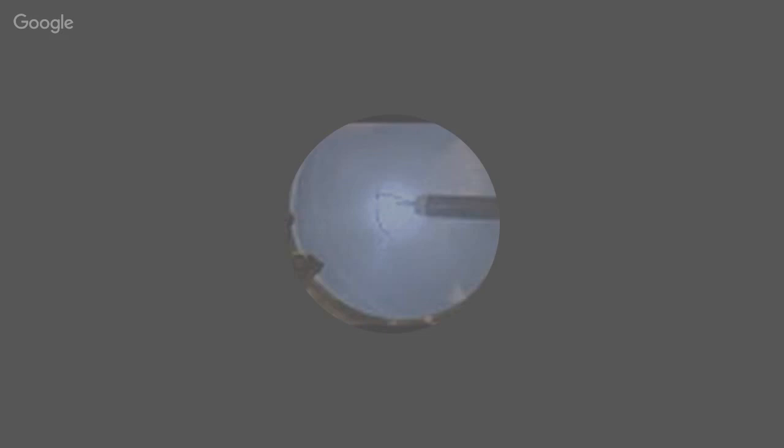So this is another demonstration problem. Here we are plotting density contours inwards in an annular region between 5 and 50. And this kind of an initial condition gives rise to converging shocks and a diverging expansion wave. And the shock reflects, bounces off from the axis of symmetry, and interacts with the outward propagating waves.